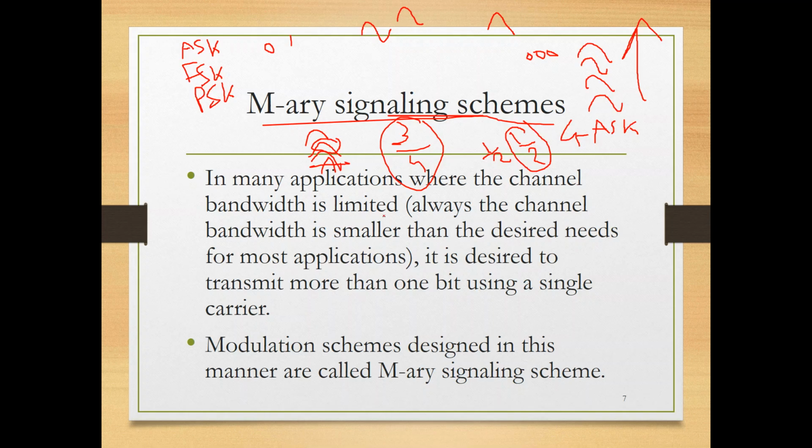So, also, when the channel is limited, you know, bandwidth is money. You buy it for millions of dollars. We agreed on this in several lectures. So when you are limited in bandwidth and your application usually requires too much data rate, you have to use high order modulation so that you can provide high data rate. Even if you degrade, even if you encounter errors, for example, video and voice, let it go. The most important thing is that you serve the customer. If a frame was in error, it's just a frame for a fraction of a second.